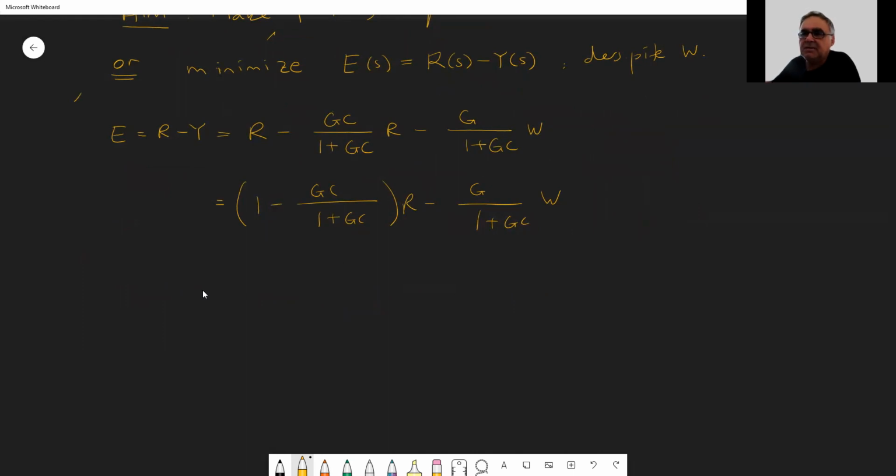So the final expression for the error E of s is as follows: 1 over 1 plus gc r of s, minus g over 1 plus gc times w.